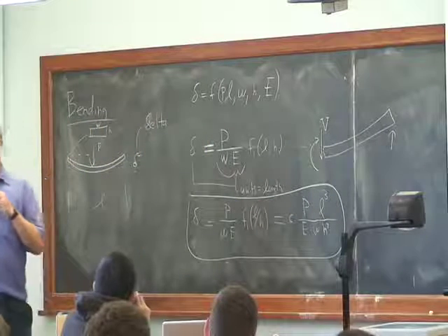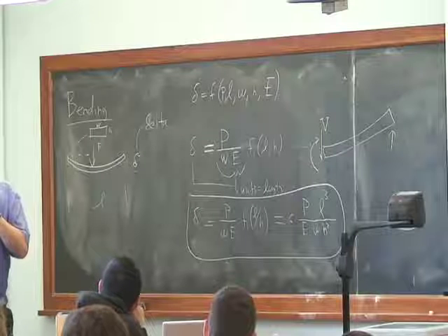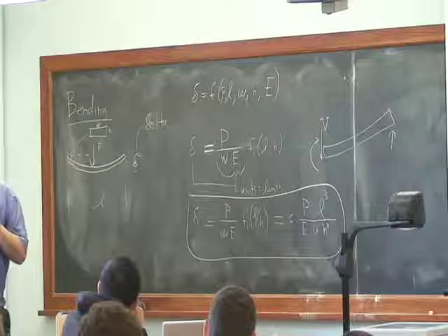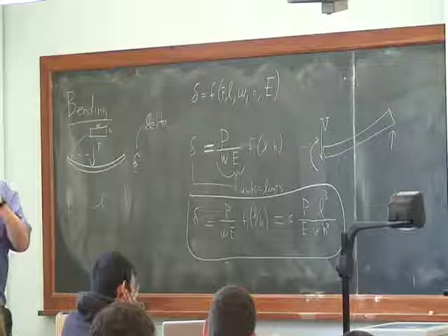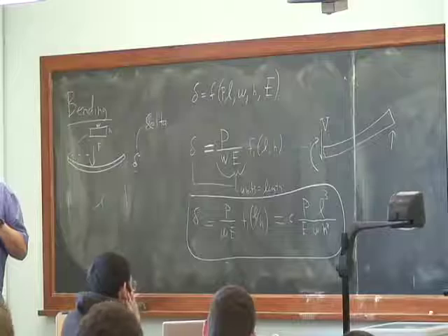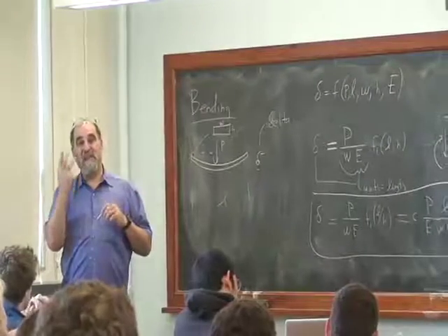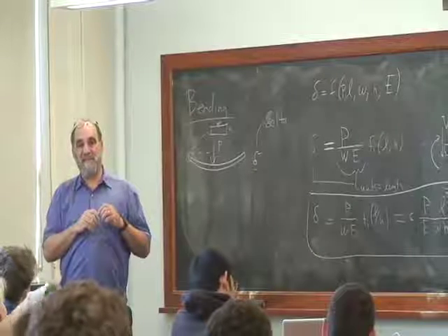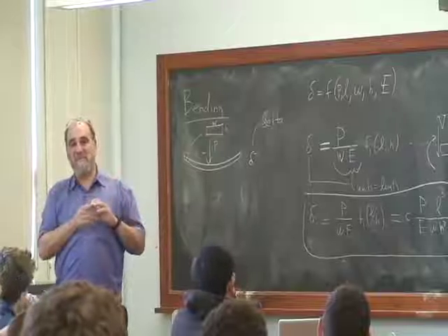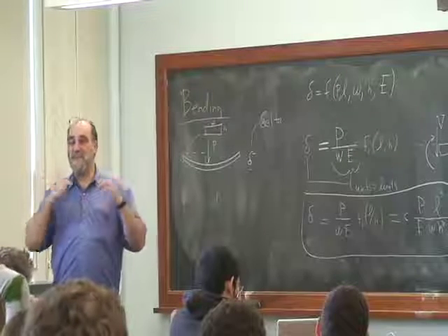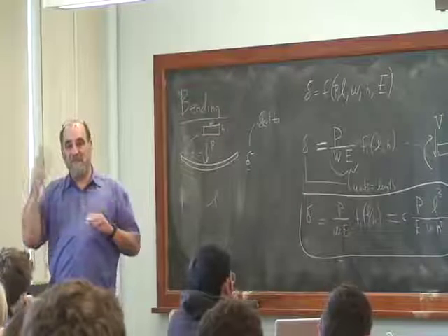Similarly, the stiffness goes up with the cube of the thickness. If you have a thicker piece of wood, it's twice as thick. It's 8 times as stiff. Huge dependence on stiffness. If you have square pieces and you have one square piece with twice the dimensions of the other, it's got 4 times the area, but it's got 2, 4, 8, 16 times the stiffness. Because the height went up by a factor of 2, and we get a 2 cubed, and the width went up by a factor of 2. So the bending stiffness increases hugely with the thickness of the material in the bending direction. That's the intuitive thing you want to remember.